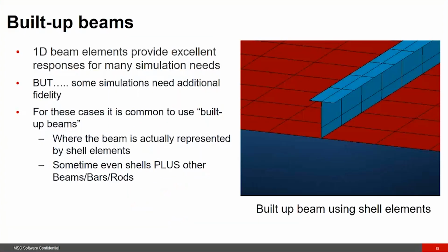And we are introducing a concept called built-up beams. See, 1D beam elements provide excellent responses for many simulation needs. That's what is being predominantly used. But in some cases, for a high-fidelity model, the beams need to be represented by maybe the shell element or a combination of shells and the beams.